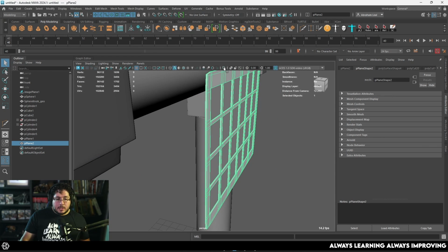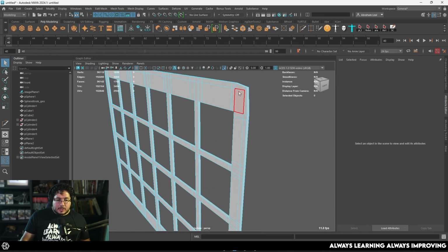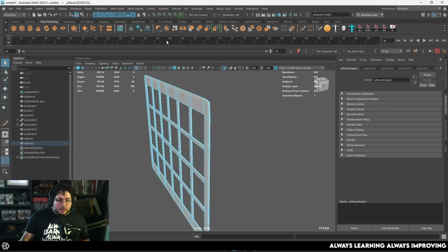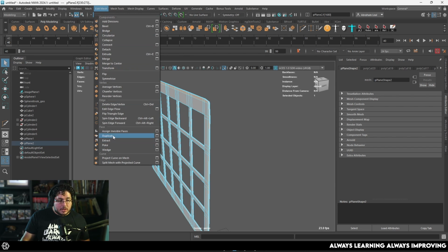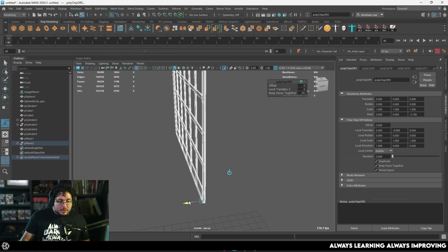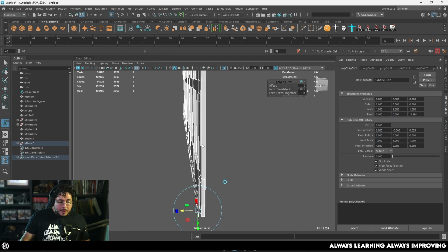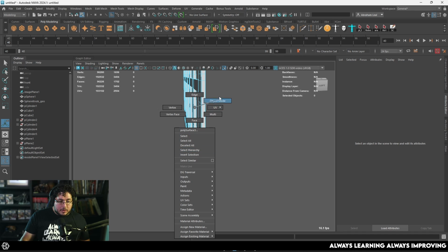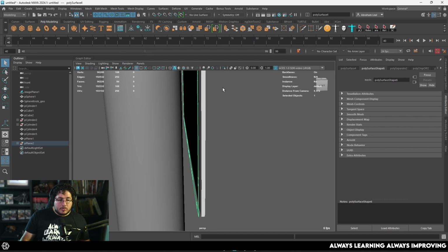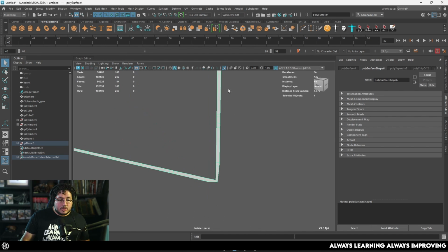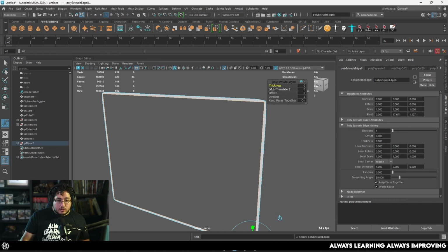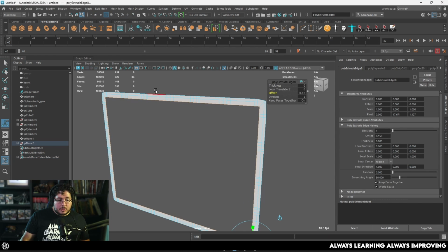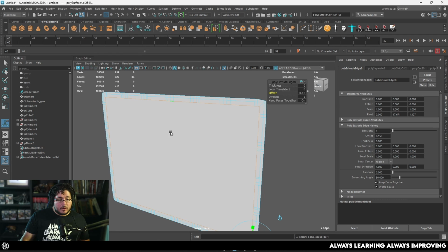So to do that and to save myself a little bit of time, I'm just gonna duplicate this again. So mesh display, where is it? Sorry, edit mesh and then duplicate. Push this out or back. There we go. And again, no need to worry about topology too much. This is just a flat area, so we should just grab all of this thing, Control E, offset it a little bit to create another edge loop, and then mesh, fill hole.